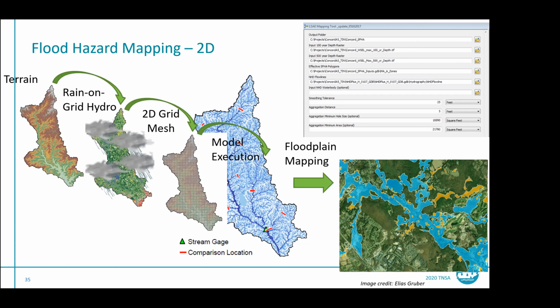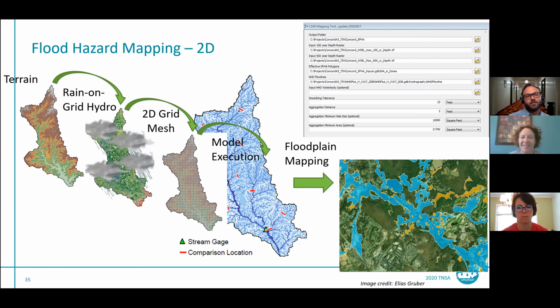anything you want under it to help tell the story about what your floodplain issues are, your base floor elevations and your existing floodplains. How tight that 2D grid mesh is depends on your level of service. It's probably unrealistic to have a 2D grid mesh for this entire basin, but if you have an area where you have seen in a coarser model that there are issues, you could always add a mesh in a very specific neighborhood or floodplain to try to get that accuracy later after you've looked at the entire system. That precision is probably the better word.